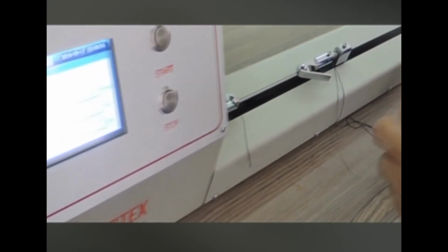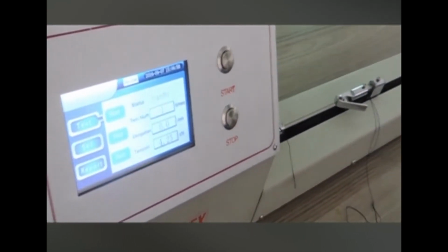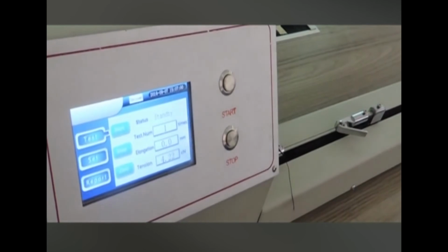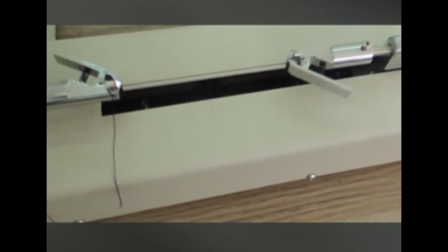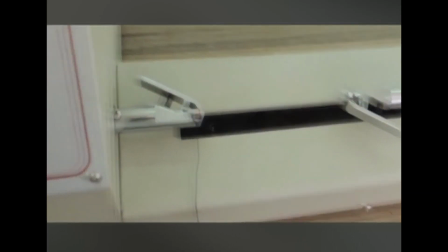In this way, the thread is transferred from the cloth to the crimp tester without a loss of twist and with a minimum of handling. Several crimp testers are available, and the Shirley crimp tester may be one of them, which is used from the beginning. The second gripper is slowly moved away from the first gripper till the thread straightens. A pre-tension may also be used for indicating the final point. The length of the thread can be read easily from the scale which is placed below.